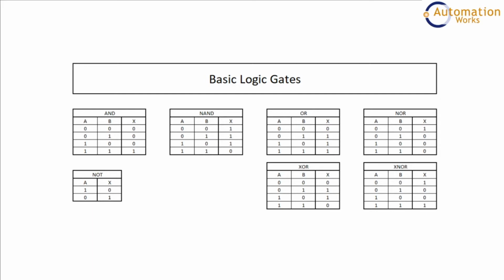These are the AND gate, NAND gate, OR gate, NOR gate, exclusive OR gate or XOR, XNOR gate or exclusive NOR, and the NOT gate. They fall into 3 categories: NOT, AND, OR. The NOT gate is special because it takes only 1 input, and the others take 2 or more inputs and calculate them to 1 output each.